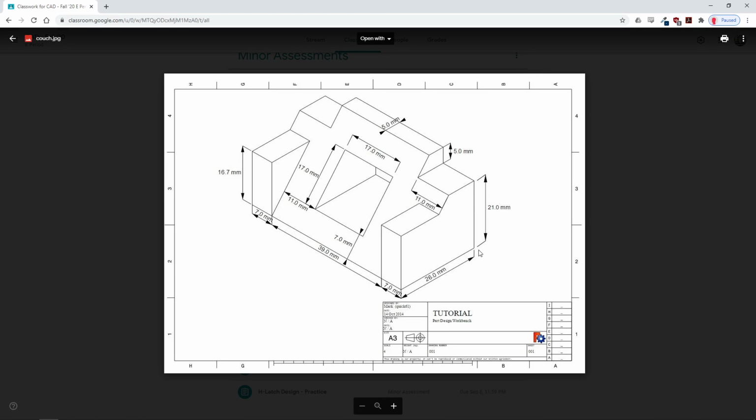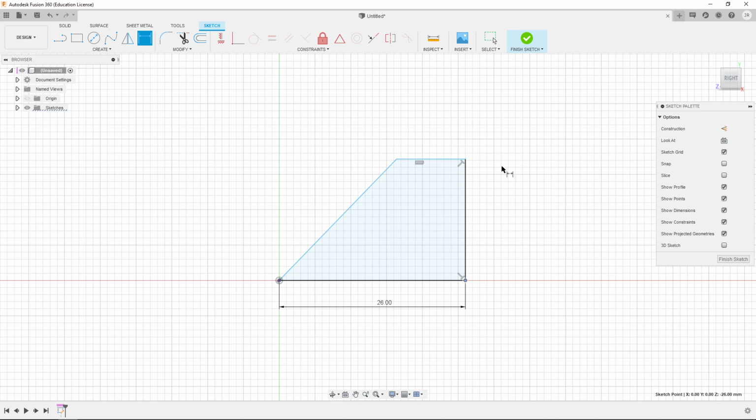So now let's try aiming for the height of this thing. From here to this cutoff part is 21 millimeters, but if we recognize that this is actually the tip over here that our drawing is, the total is 21 plus 5, which is 26. So we're going to come back, and we're going to dimension this line as well. So I'm going to click it once. And this is much too short, it's 17. I'm going to click on it, and I'm going to type 26.